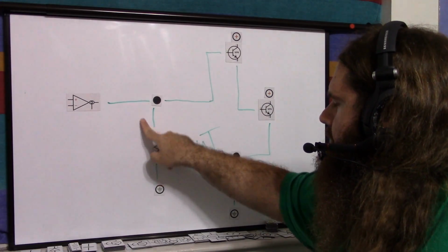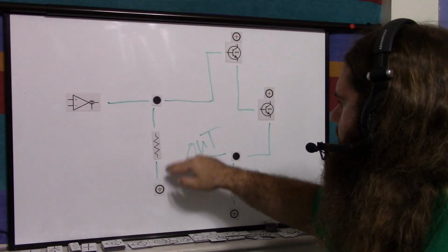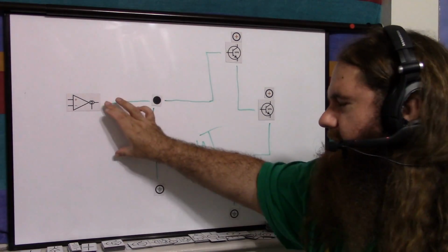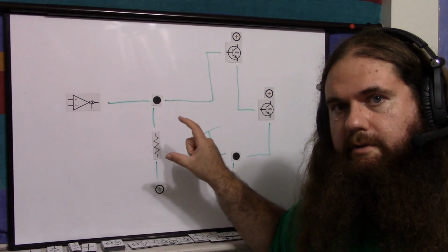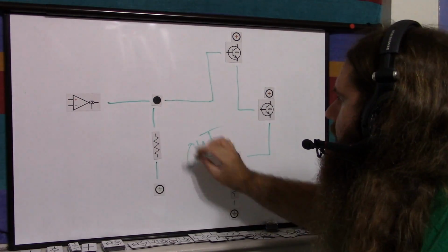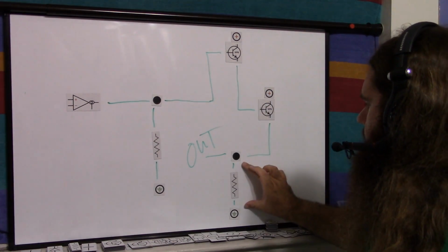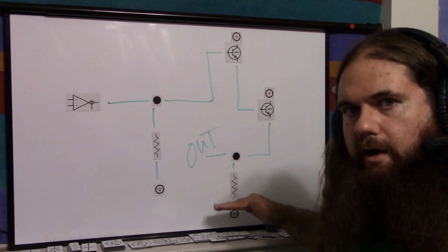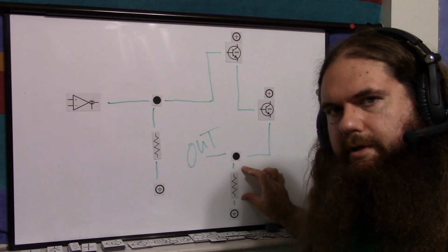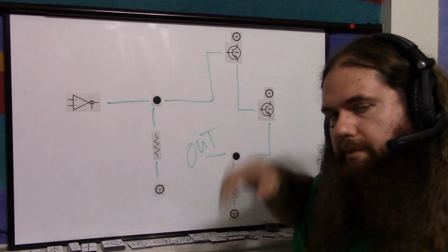The OTA is seeing a constant effective impedance, and it's setting the voltage to put a certain current through that effective impedance. And so you get a voltage drop here, across these base to emitter junctions, and this follows, and then this gets whatever current it needs to get the same voltage drop over there plus that.